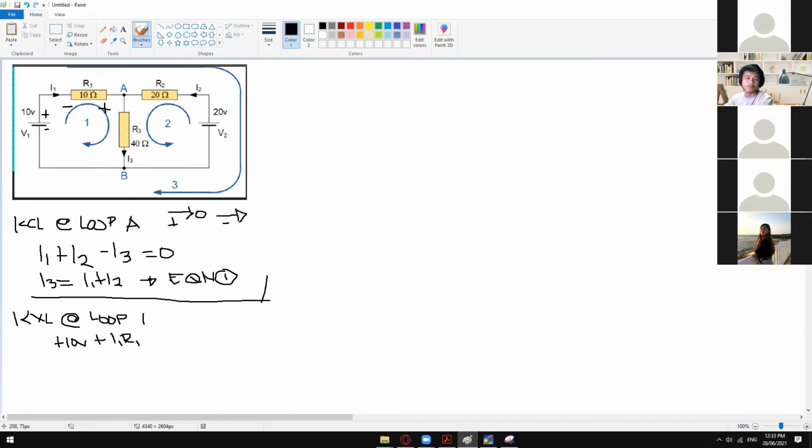So remember, as our voltage source passes through a load or a resistor, it will give us a voltage drop. But in here, we have another voltage source right here wherein they are being added with each other. So we could not say that this is a voltage drop anymore since it has a sign of positive.